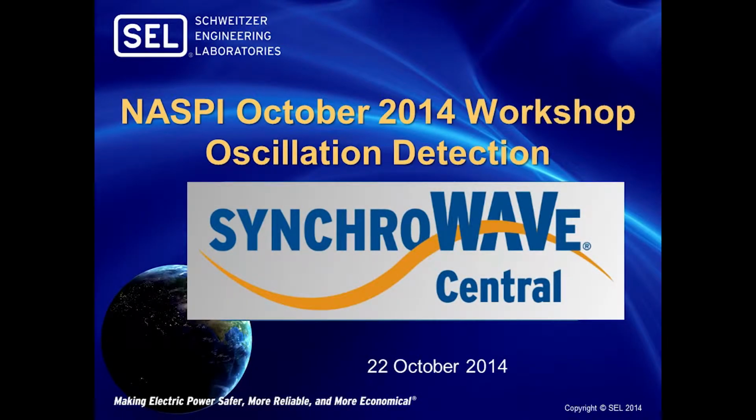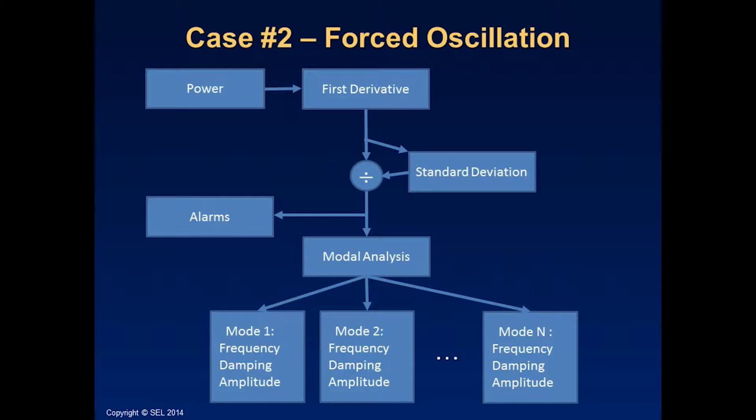This video will demonstrate SEL's Synchrowave Central software as applied to the NASPI 2014 Oscillation Test Case number 2. Modal analysis is run on the first derivative of generator power, normalized by its ambient standard deviation. The signal is also passed to the alarms processor.